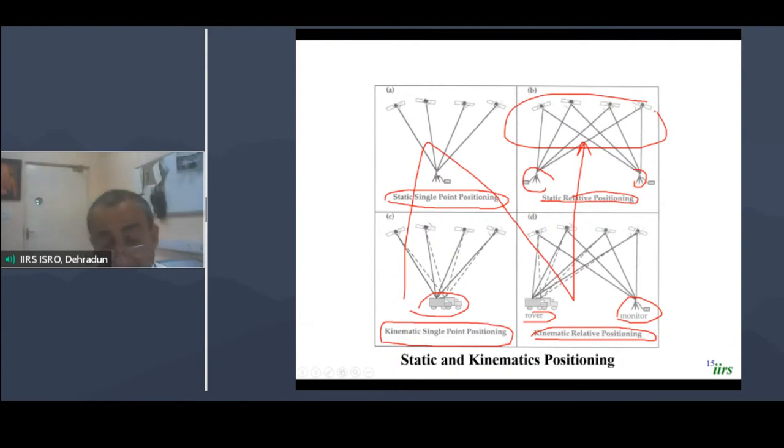These carrier measurement capabilities are generally kept in geodetic GPS receivers, which are single or dual frequency, where you want accuracy of say 1 centimeter, a millimeter or a fraction of a millimeter, which is geodetic dual frequency. There you can go for carrier measurement. Otherwise, 80% of jobs from GPS or GNSS can be done through the code measurement technique. Like in a mobile phone, the GNSS chip basically uses the code measurement technique, not the carrier one, because the carrier one is more bulky and has so many other capabilities so that it can resolve the ambiguity and so forth.